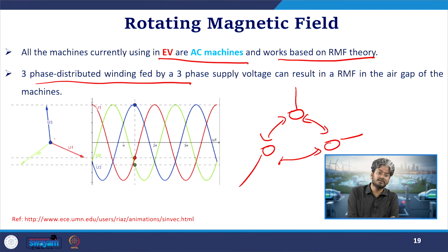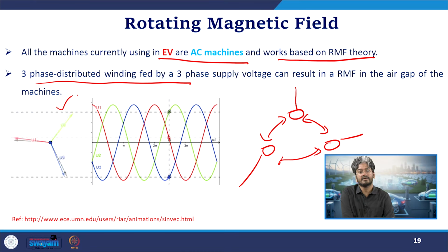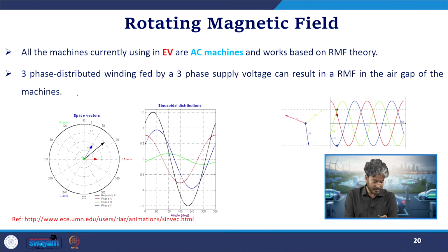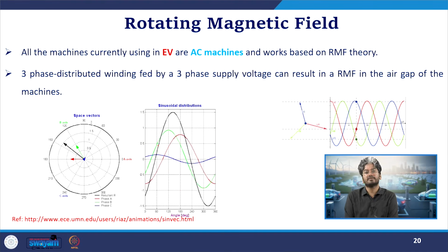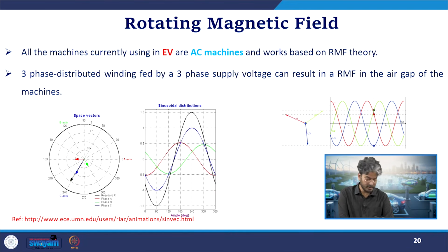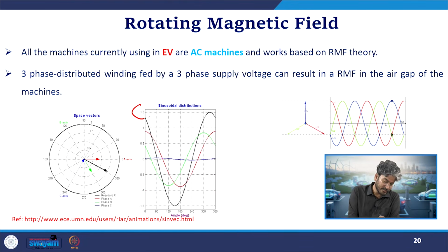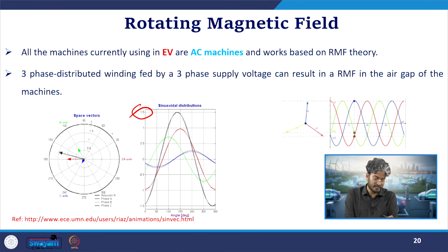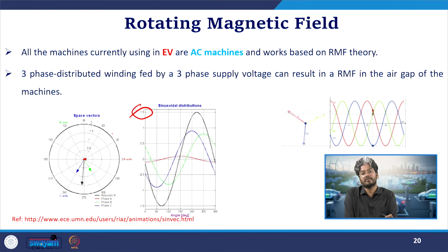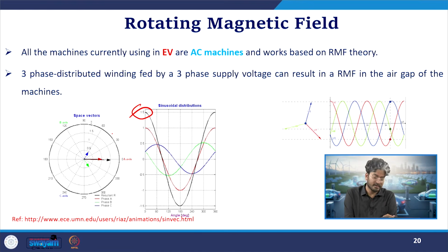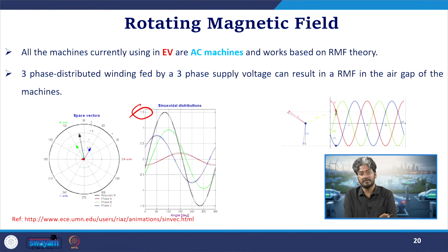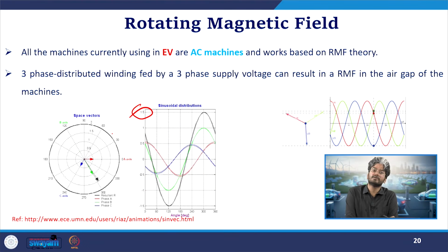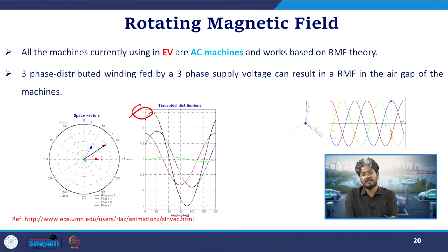So when we meet these conditions, over here if you see we have given a 3-phase balanced supply and its instantaneous variation is shown over here. When I see the resultant of these 3 supplies which are given to the 3-phase distributed winding, I will see that in space I will be having an effective rotating magnetic field which will be having 1.5 times of magnitude. We have discussed this in more detail when we were in the inverter circuits. There we have used this concept to control an inverter, whereas in this case we are using that inside the electrical AC motors.